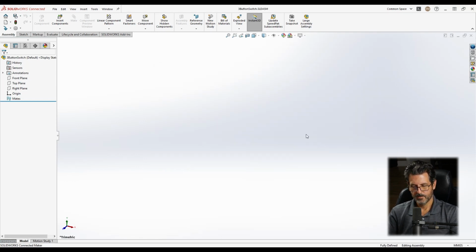Save it. Now we have an assembly, and I like to work in assemblies and then create virtual components inside those assemblies. Then you only have one file out there, and it's an easy way to develop, so you don't end up with all these extra files. If the design doesn't go forward, you don't have all these extra files hanging around. So, all right, we have that.